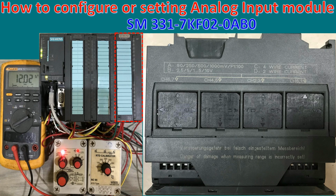I will use the current loop calibrator and RTD calibrator to set or source the signal to the module, and then use the multimeter to measure the current output from the analog output. Okay.